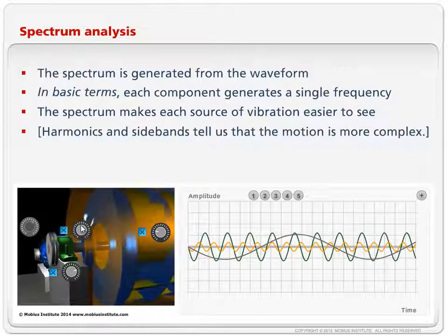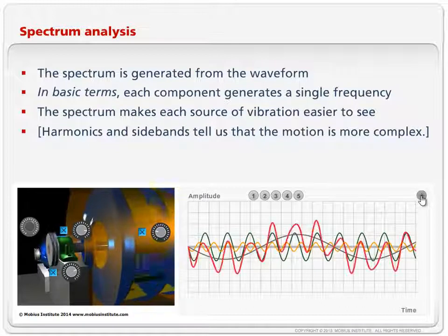Unfortunately, this is not exactly how it works, because we don't see those three nicely coloured signals. We see the summation of all three. They add together, they combine to make the housing of that bearing move according to this red line, and that's what the sensor feels. That's what this accelerometer feels, and that's therefore the signal that goes up to our data collector. So that's what's happening.